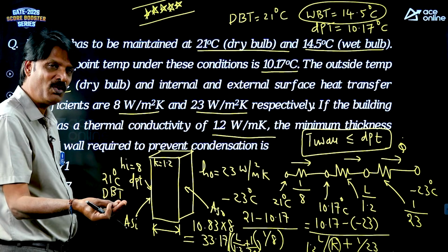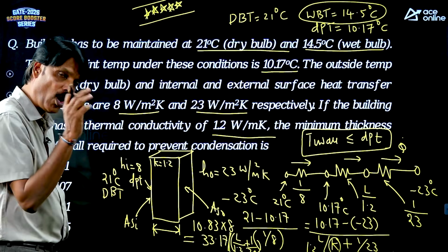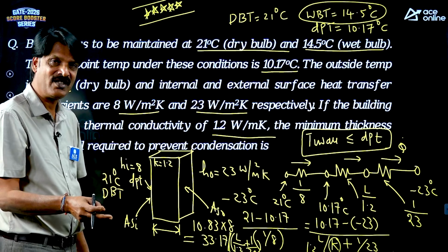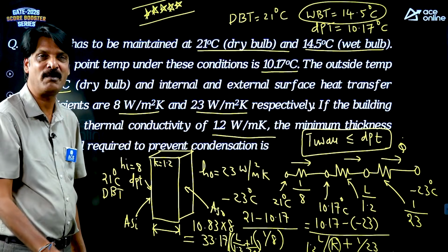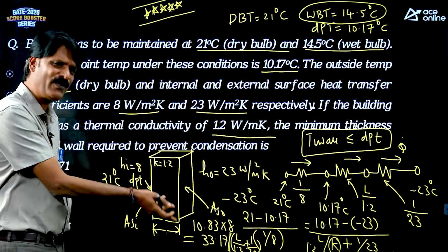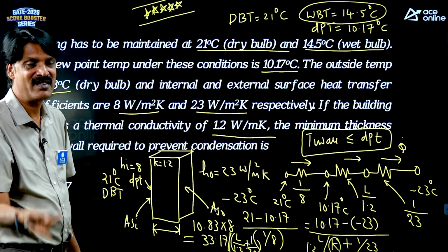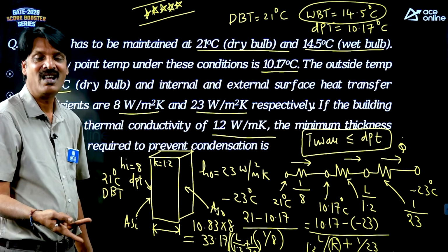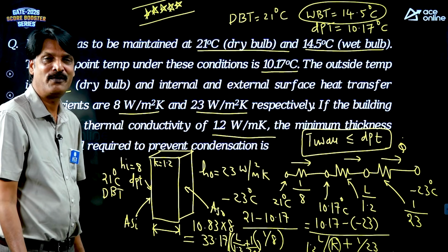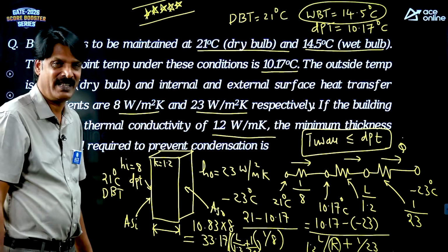So, any amount of moisture that is present in the air has already condensed, and it has reached its freezing point. Hence, you observe ice formation on the outer surface. Thermal conductivity of ice is less than the thermal conductivity of water. Its value is around 0.4 to 0.5 watt per meter Kelvin. It acts as an insulator again.